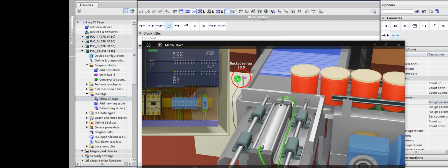All right. So don't be confused when I said the sensor shuts down this, activates this, and you are aware that sensor has only three cables. You'll be surprised why only one cable will activate this and deactivate it. No, the sensor is activating a relay. The relay is responsible to shut down and put on so many circuits, so many signals, so many items. Okay, so I can have a sensor, I can have a relay that has 4 circuits. So in that case, I'm going to activate 4 items or 4 equipment at the same time, or deactivate them at the same time, depending on the sensing instruction that is coming from my sensor.